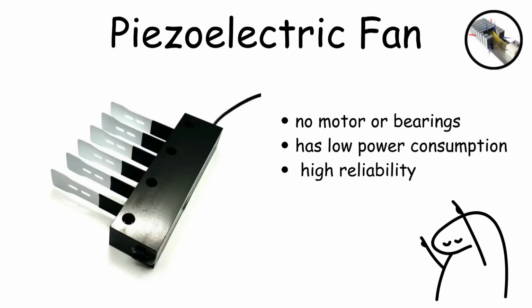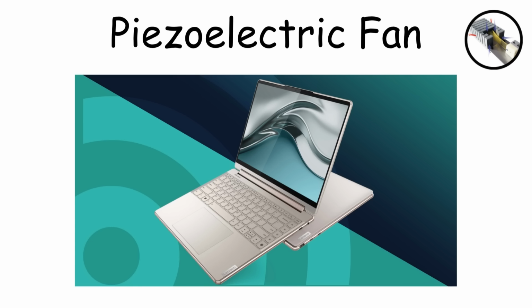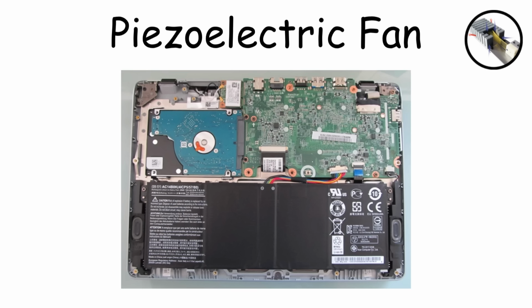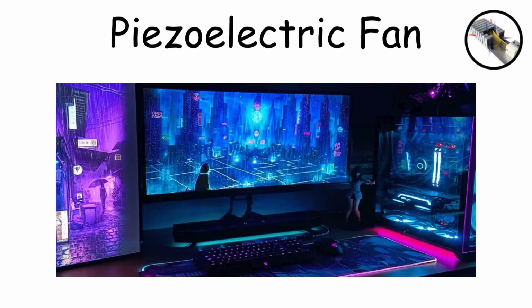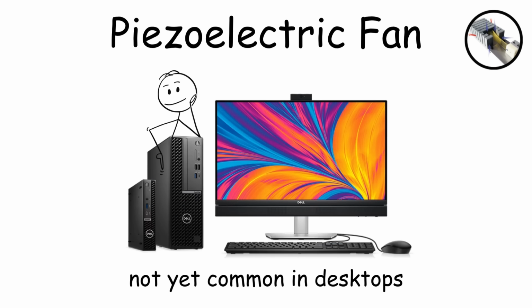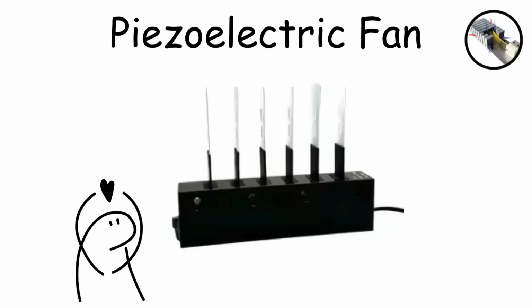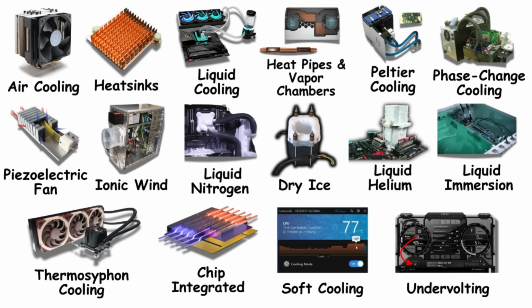With no motor or bearings, it has low power consumption and high reliability, useful in slim laptops, embedded systems, and fanless designs. However, its cooling capacity is limited. Piezoelectric fans generate less airflow than traditional fans, making them less suitable for high-performance or heat-intensive systems. They're not yet common in desktops, but for compact, low-power devices, this technology offers a clean, efficient solution.